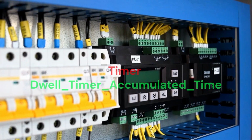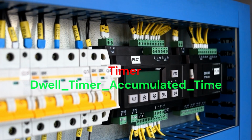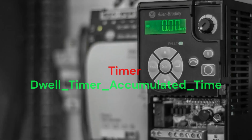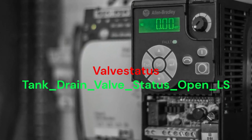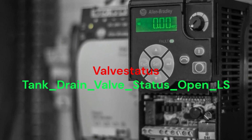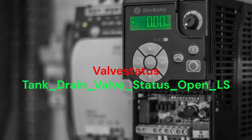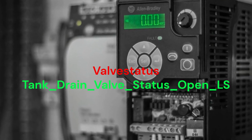Bad: Timer. Good: Dwell Timer Accumulated Time. The good name clarifies the purpose of the timer and what the value represents. Bad: Valve status. Good: Tank Drain Valve Status Open LS. The good name uses a clear structure and identifies the specific type of sensor.